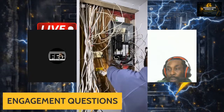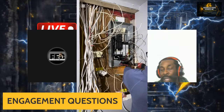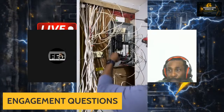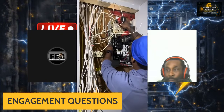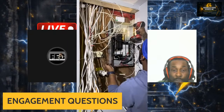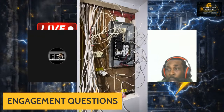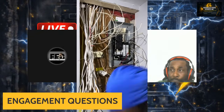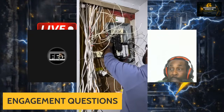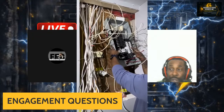So again, this is a job that I'm working on, and it goes back to the actual breaker topic. I have a limited time during the day. The importance of labeling the circuits once you're about to close off your inspection job is very important. Always make sure to label your wires before you actually change out your panel. It saves you on troubleshooting, saves you on pulling out the actual circuit breaker finder.